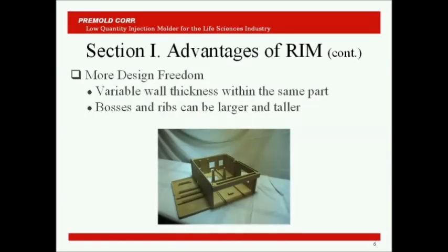And a particularly important advantage of the RIM process is greater design freedom. Parts can easily be designed with variable wall thicknesses, tall bosses, minimal surface draft, and other complex features with less rigid ratio restrictions.